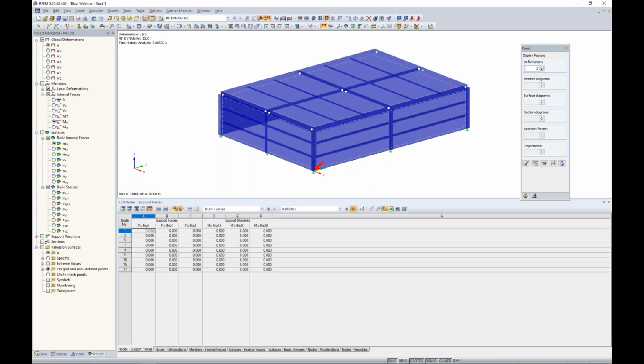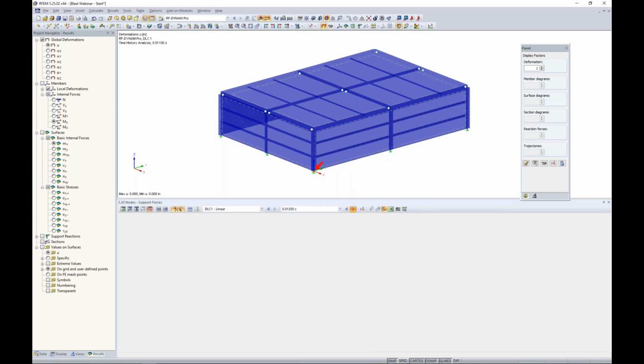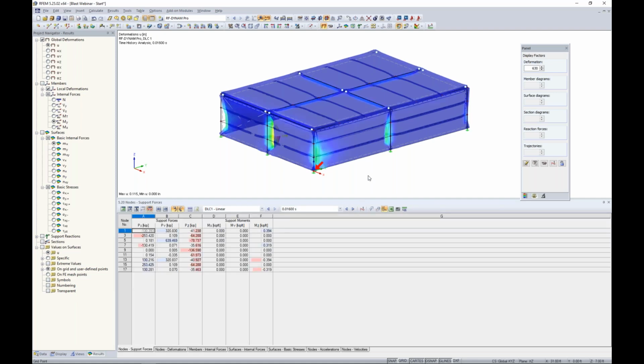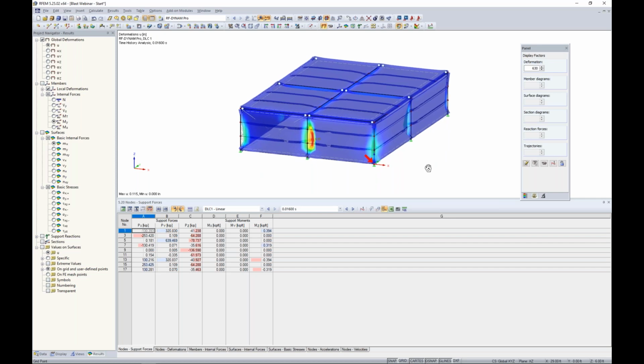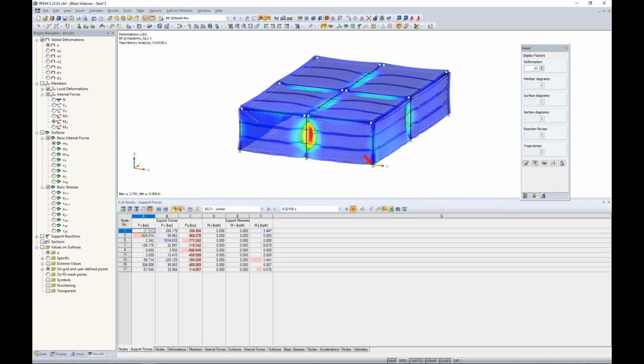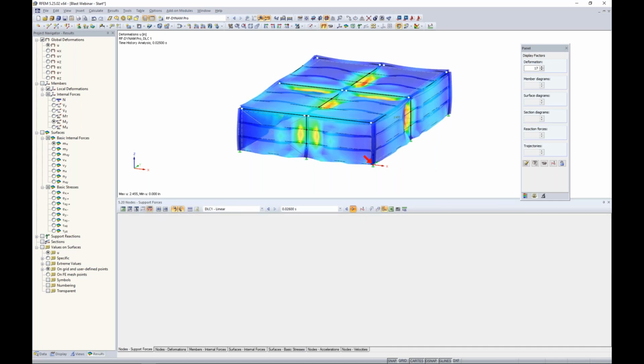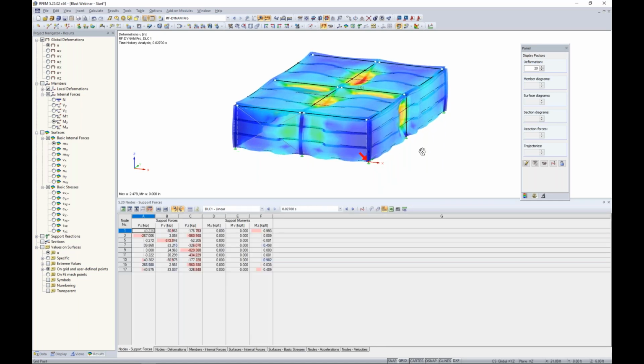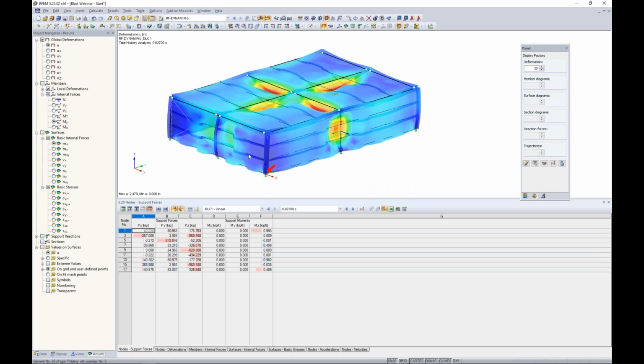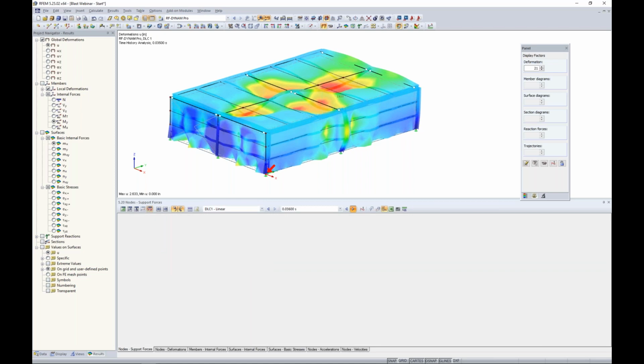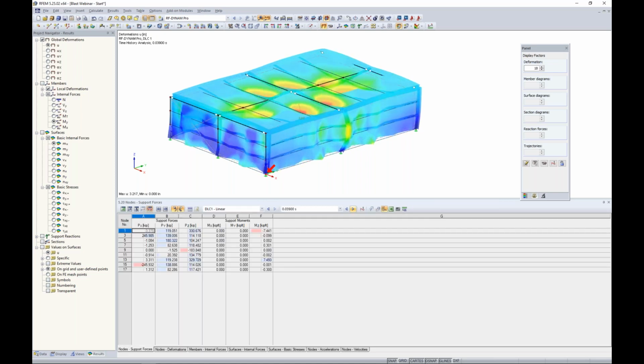Remember, nothing's happening on our structure until we have that estimated time of arrival at about 0.016 seconds. And that's where we start to see this blast load impact our structure. We continue scrolling through these different time steps to slowly see that wave load travel from the front of the structure to the center and the roof and clear back to the rear of the structure.